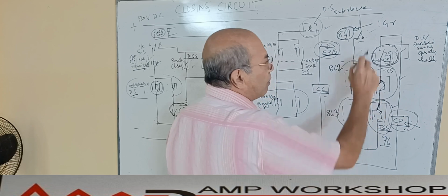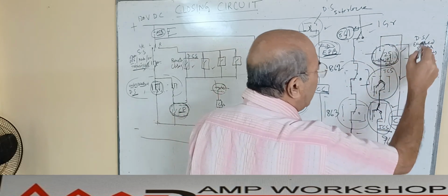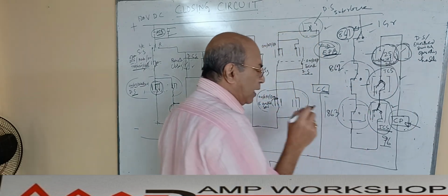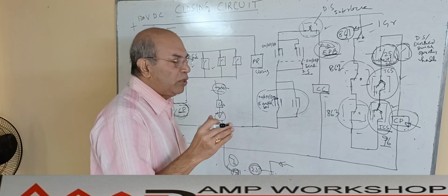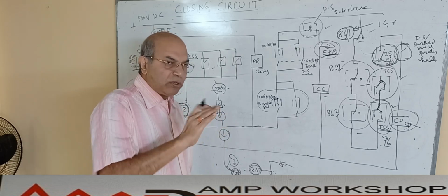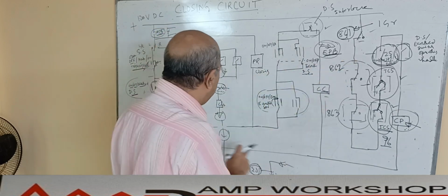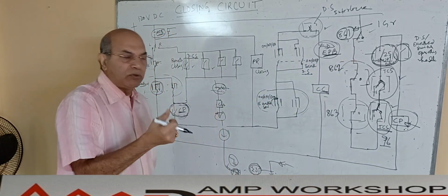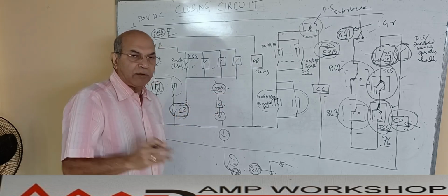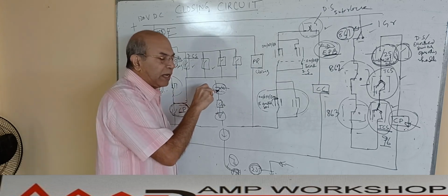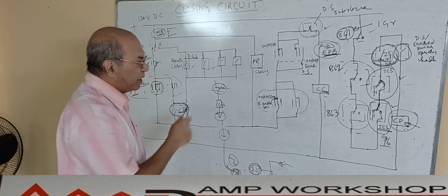When both interlocks are met, and if any other interlock is required, there is another interlock over here. In addition to this, suppose the switchgear I am going to close, I have put the isolator on, but I have not removed the handle. You know, in the fixed type switchgear, this isolator open and close I can do by motorized operation, and also I can do manually. There is a rod, I will insert the rod inside, then I will rotate it to the respective position.